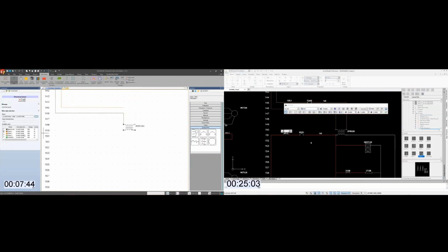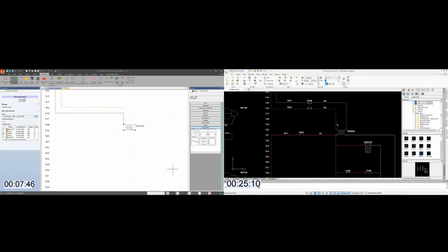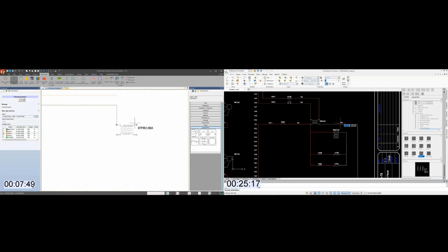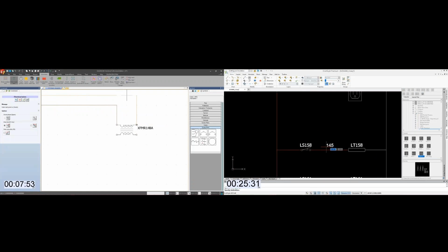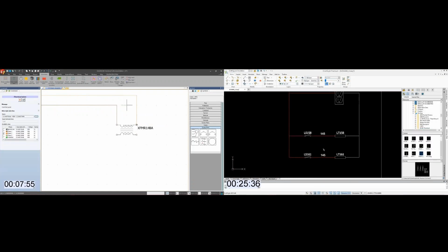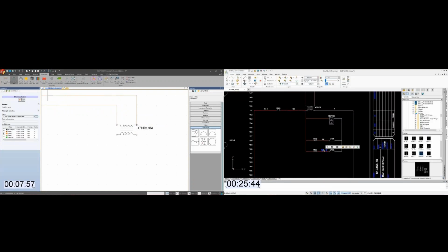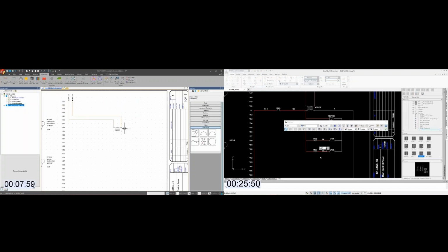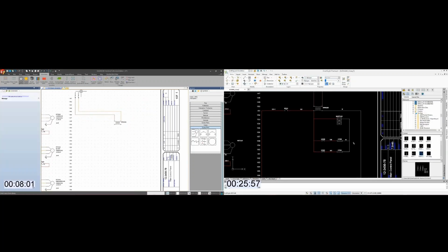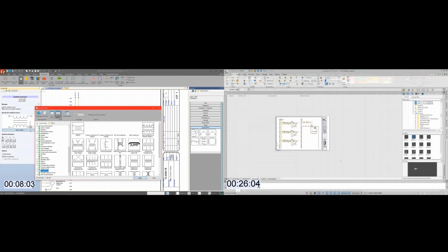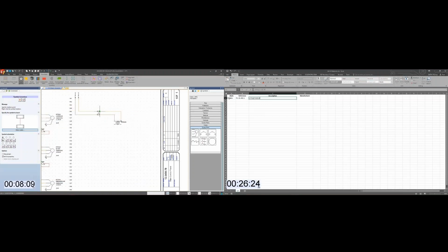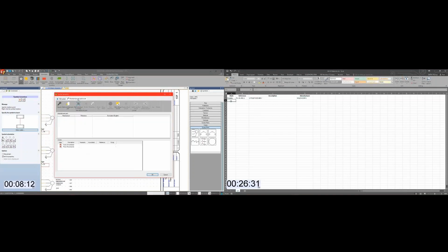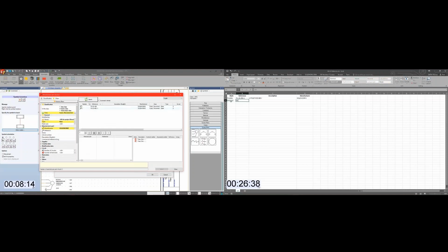In Electrical, at 7 minutes and 45 seconds, I'm still building out my project circuit, just defining wires. Again, I'm ensuring that all these wires are of the appropriate wire type before I place them. And again, it knows the size, color, gauge, and physical properties of these wires. There are a few more dialog boxes involved when you work here in SolidWorks Electrical, but we're capturing a lot of the data on the front end, dramatically adding efficiency on the back.